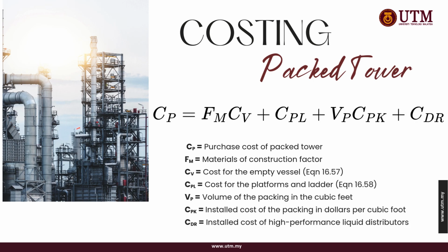Now I will explain how we are going to estimate the cost of a packed tower. The packing inside the tower helps with the mass transfer between the fluids, and this packing comes in two types. The first one is dump or random packing, and the second one is structured packing. The formula shown here is the purchase cost of a packed tower.